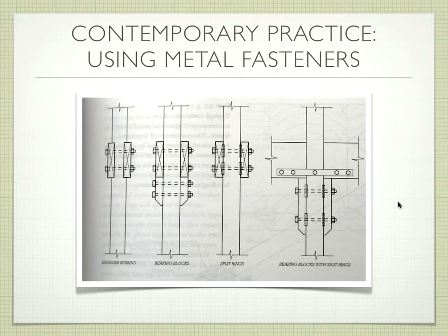So heavy timber is as long as the tree and no longer. Engineered lumber can be longer than the tree because we're laminating pieces together. That's the key. Is that different than glulam? No, that's what I'm talking about, glulam. Engineered lumber includes some of the other pieces that we've talked about, but in the heavy timber world, the only thing that is used is the actual glulam, because it's still a big mass of wood.